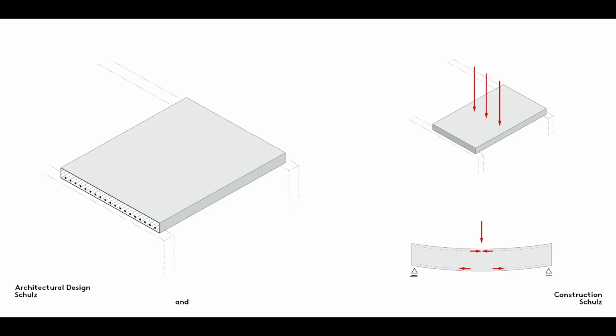As a result, the reinforcing steel bars, or rebar, should be placed at the specific points at which tension forces occur. In a non-cantilevered floor, tension forces occur at the bottom of the slab, and it is here that rebar should be positioned. The steel must be entirely sheathed in concrete to avoid corrosion.